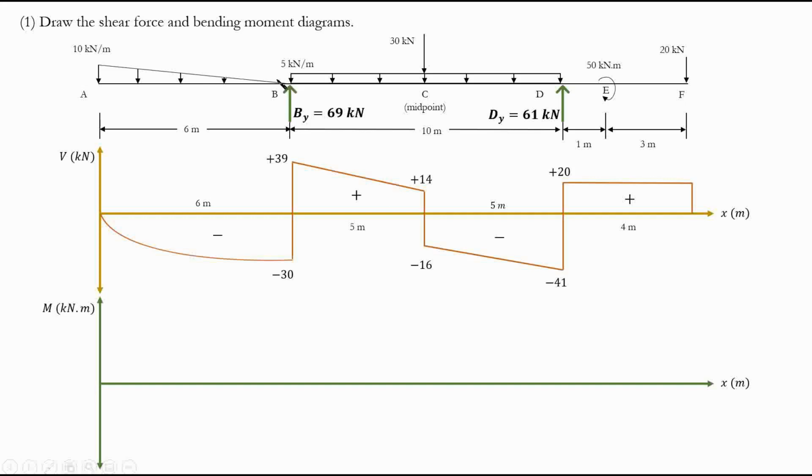And in this case, think about it. Here we have a shear force and moment, and we are only concerned with moment here. We want to find the moment here for the moment diagram. Although we have access to shear here, in most cases we don't need the shear. So in this case, I don't want to deal with the value of shear. I don't want to find it. That's extra work. So what I do is just take the moment about this point, where the moment effect of the shear is going to be 0. In other words, the lever arm for the shear force is going to be 0 about this point, because it's going through that point. Of course, you will understand this point better when we are dealing with a section cut in, I think, question 5 or 6.